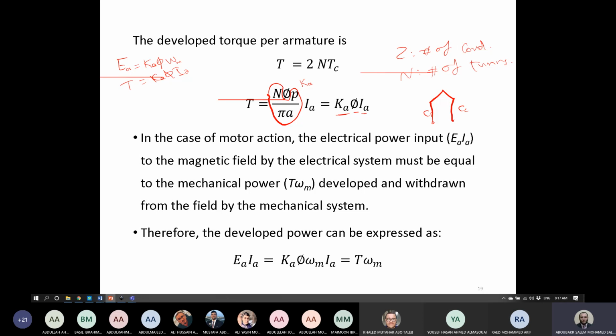In terms of power, when you supply a motor, there will be some losses. Some electrical losses on the coil equivalent resistance, which we call copper loss, like what we described previously in the transformer. After that, you will also have some core losses, and the remaining power will be converted from electrical power to mechanical power.